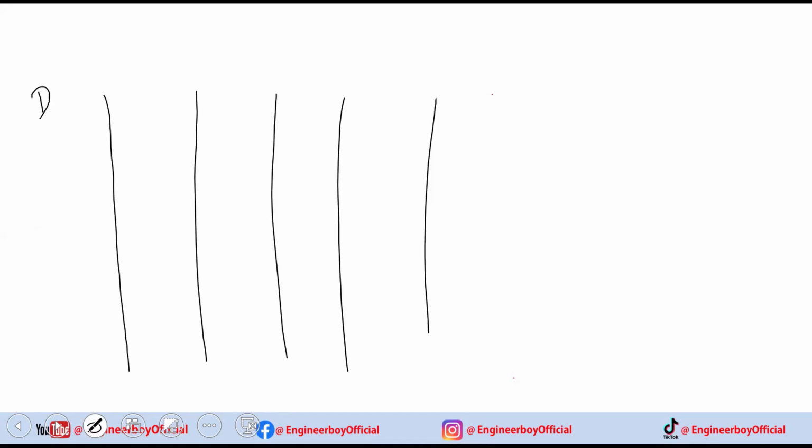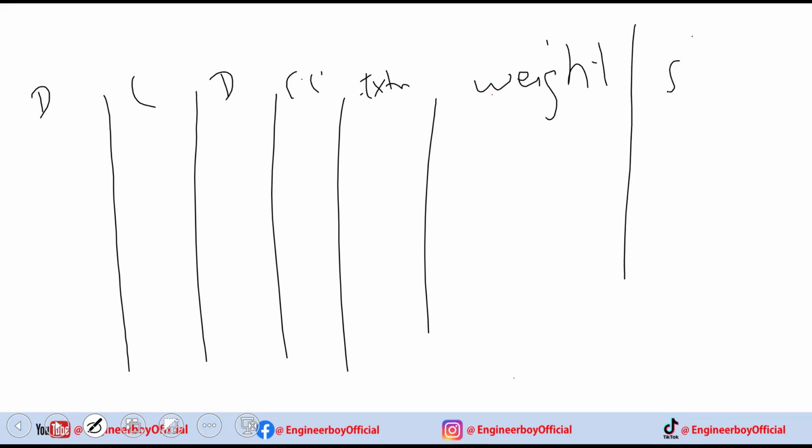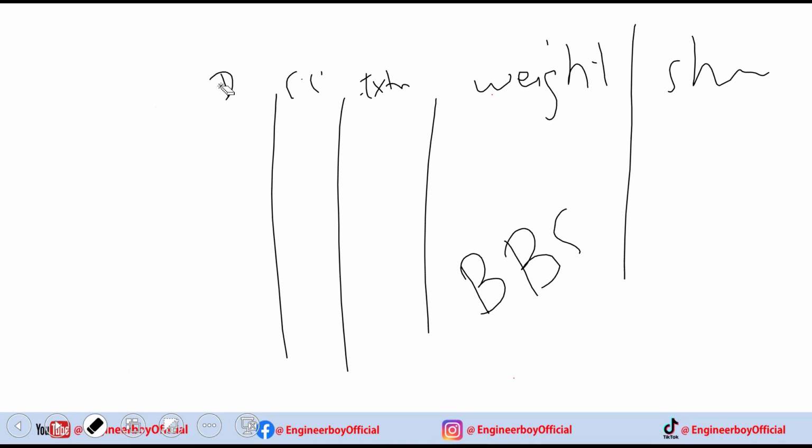Yes. So bar bending schedule is actually what we do on a whole page, we do those things only in a table. So bar bending schedule is just a table. It's very simple. It is like a table, and we put everything over there, like the description, then the length of the member, the diameter, maybe the concrete cover, the extra length. Every one of these things, and then maybe the weight of the bar, and maybe the shape of the bar, etc. So putting all these things in a table is just the same thing as BBS or bar bending schedule. That's nothing that complicated, okay?